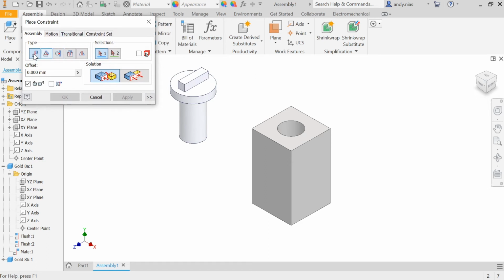We're still going to be using what Inventor terms a mate constraint, but as you'll see, the options for the solution will change shortly. So all we're going to do is hover our mouse over the cylinder, and you'll see we get a center line and an arrow showing us the axis. Any cylindrical surface would have it, so that slightly wider one also, and then if I come here you can see that the hole does as well. You'll notice that for the hole, the axis is pointing down, and for the peg the axis is pointing up. It doesn't really matter, but you'll see what happens shortly because of the direction of those axes.